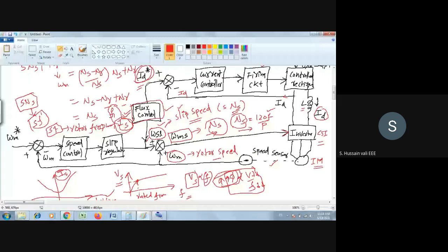The I_s which you generate here may not be equal to the reference value. How are you generating the reference value? You generate the reference value based on this graph. How do you decide the rotor frequency here? The rotor frequency is decided by the flux. So flux is the center for both your slip speed and also for the stator current.